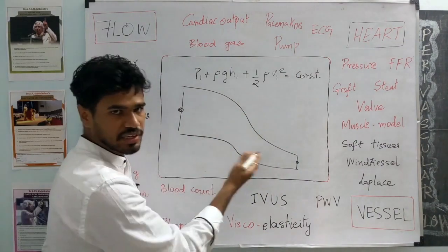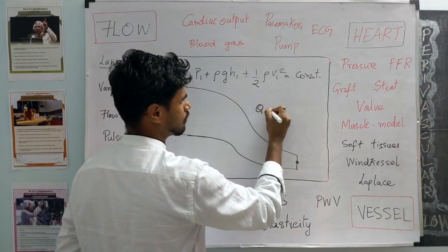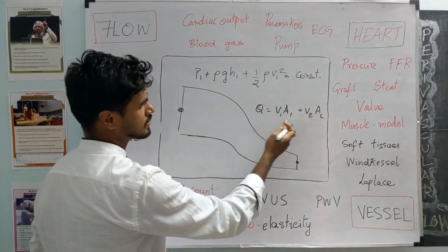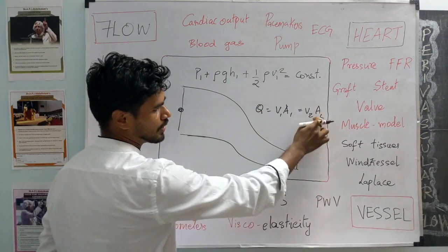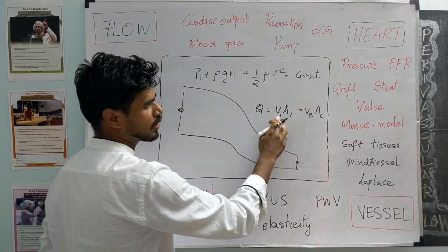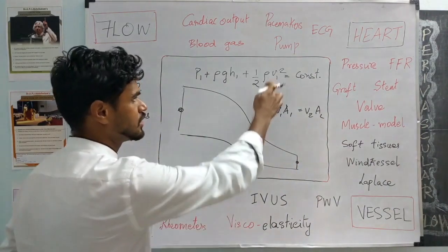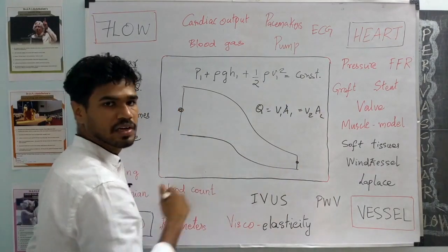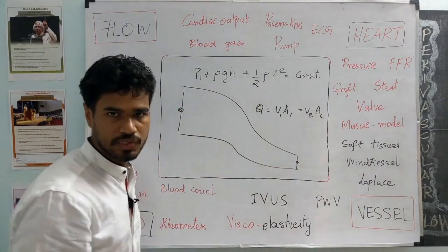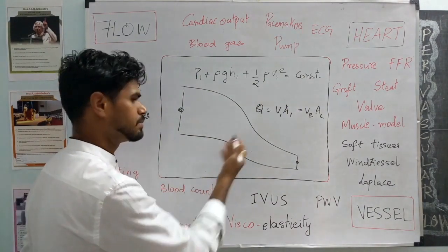An additional equation that is usually required while using the Bernoulli equation is the equation of flow conservation. Essentially, flow is velocity times A1. So flow here is equal to flow here. Given this, we note velocities and geometries are related at these two cross sections. With these two equations, we could solve most problems involving pressure and velocity variations at two cross sections. And devices like venturimeters are all designed based on this principle.